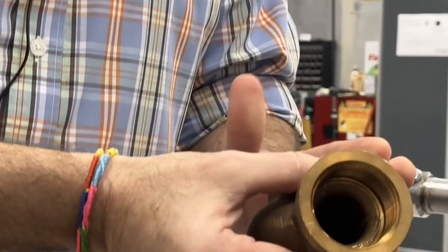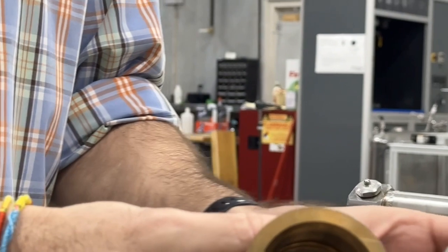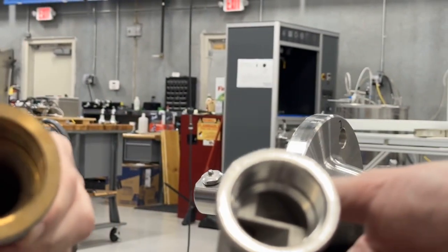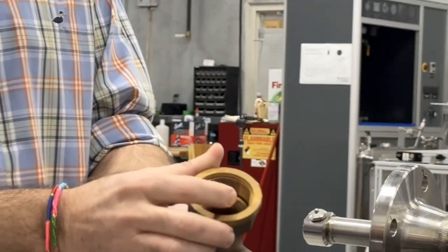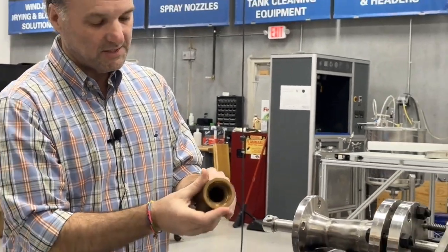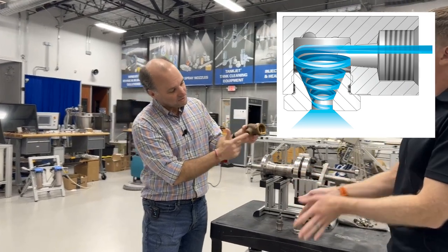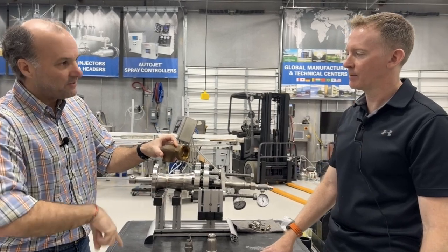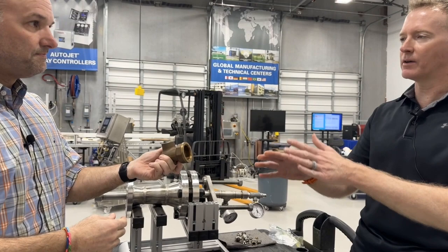So if you look at this nozzle versus this nozzle, same flow rate, same pressure drop, this one is going to have much greater free passage because there's no vein inside of here. One of the things to understand about the hollow cone spray nozzle is that when the liquid enters this whirl chamber, it spins, and that spinning causes centrifugal force, and then the liquid exits off of this formed orifice. There's actually an air core that forms in here, and then you get a round hollow cone spray pattern. And it's like a curtain of liquid coming out.